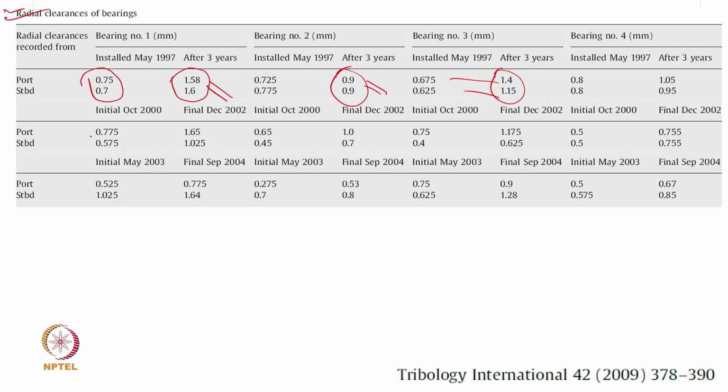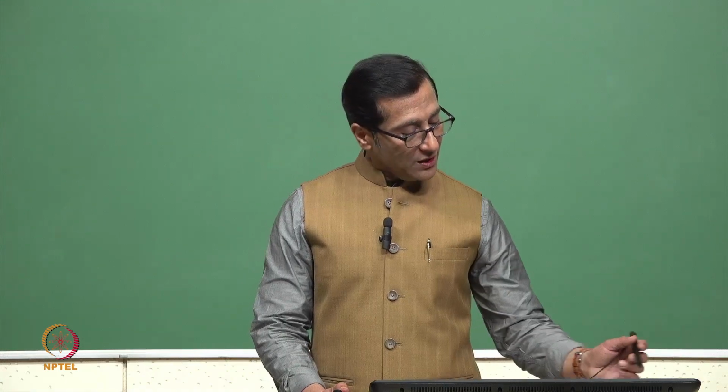Coming to the second installation: first installation, second installation, third installation, every time we find that the bearing clearance is increasing, many times 30%, 40%, 50%. The ideal situation here is to change the bearing and bring a new bearing, otherwise the losses will be more significant.